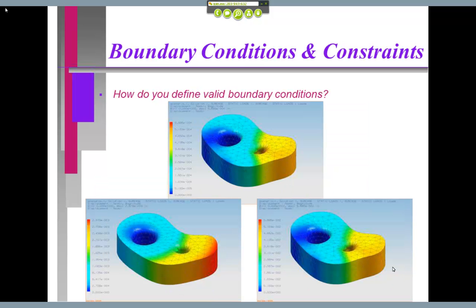Quick question? Yep. When you say a pin constraint, what is that actually? Is that constraining, what degrees of motion is that constraining? Everything? It's not like a fixed constraint though, right? It's just pinning it. Yeah. So there are lots of different types of constraints in the CAD systems. If you're doing a clamp, you're generally fixing it in all degrees of freedom. If you're pinning it, then generally it's again a fixed constraint.